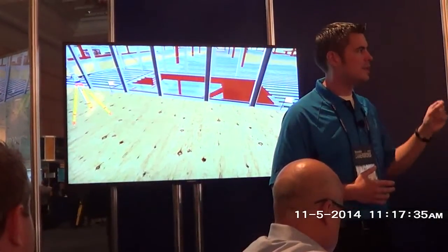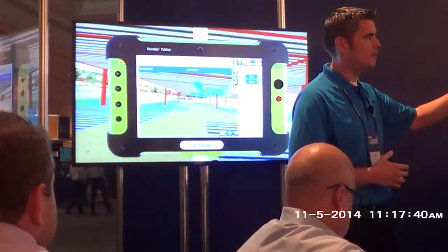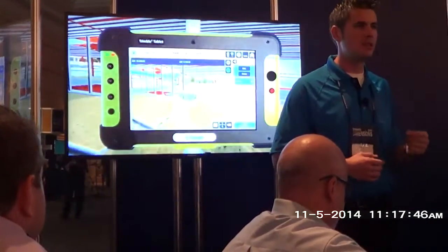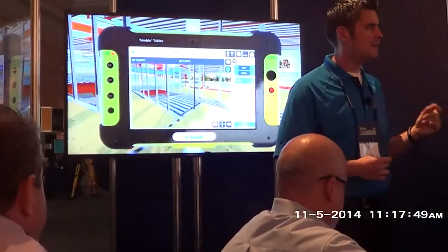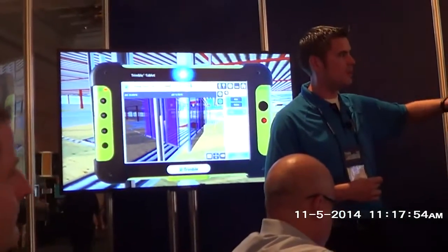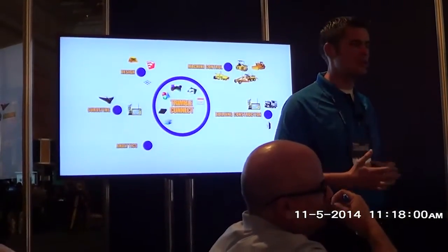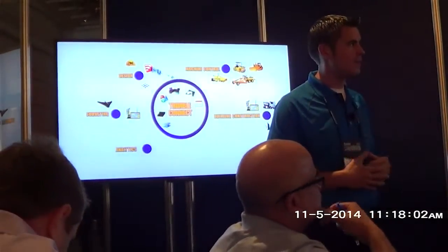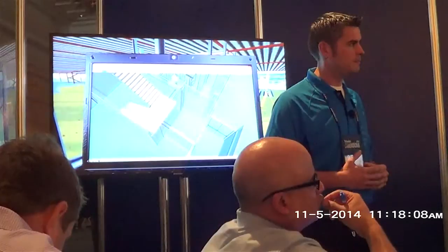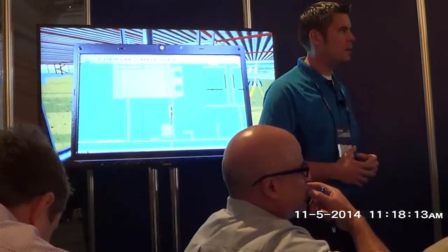That robotic total station can also send the design information into one of our mobile tablets, which is what you see right here. So on this device, as this gentleman walks through the building, he can start to experience an augmented reality. By that I mean that he's able to see design information from within that tablet before it's placed in the field. And there, he spotted a conflict. As is often the case in construction, sometimes things get out of alignment. So he takes awareness of that misalignment and he sends it on to the designer for an update. So now we go back into the design software and we make the change. We're getting the wall moved into where it needs to be.